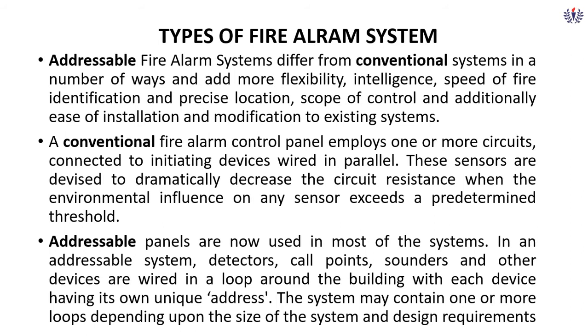A conventional fire alarm system employs one or more circuits connected to initiating devices wired in parallel. These sensors are devised to dramatically decrease the circuit resistance when the environmental influence on any sensor exceeds a predetermined value.